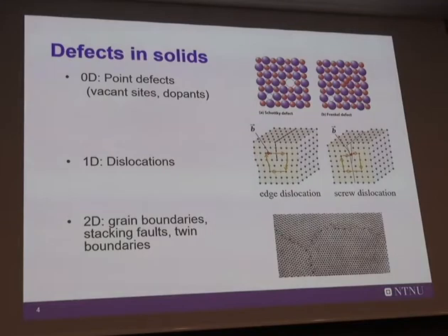If you look at the edge dislocation, it looks like you have one plane of atoms which is squeezed in between two in a perfect situation, and then the new plane is ending in here, so you can follow it into the crystal. So if you count the number of atoms on the bottom and the top here, you see there is a difference.